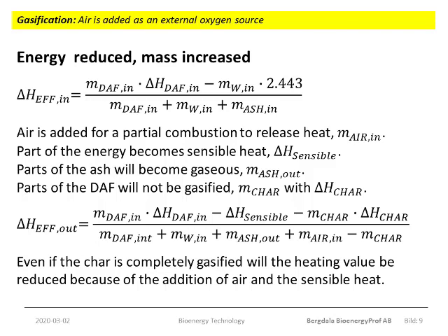It may, for example, be simpler to use in a specific process. It is easier to run a glass melting furnace using a gaseous fuel than a pulverized fuel, just to mention one example. But then, to mention another example, the ash content in the gas may be enough to prohibit the use of the gas in a gas turbine. So just gasifying solid biomass does not necessarily mean that the new gaseous fuel is free of ash. The gas heating value can be changed by using oxygen gas instead of air as oxidizing medium.